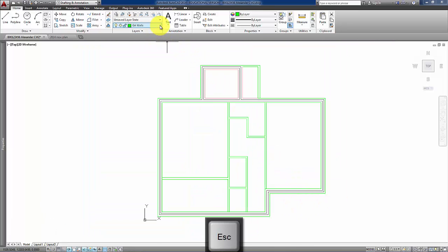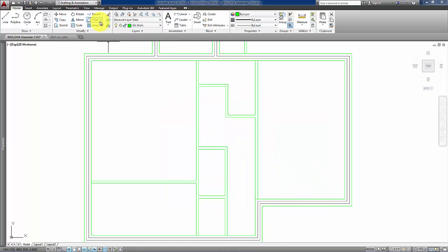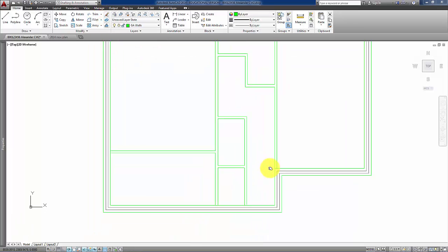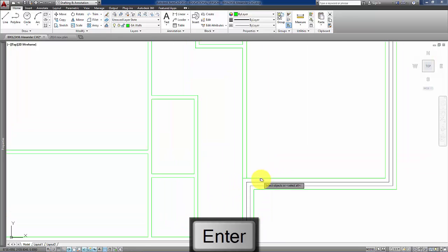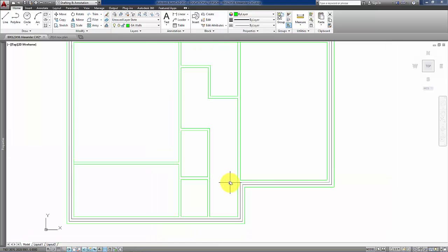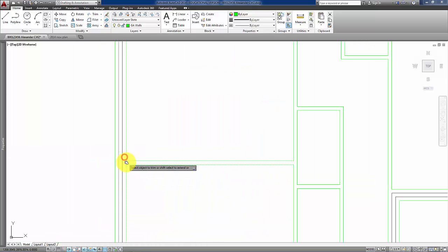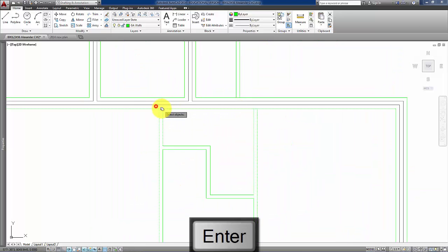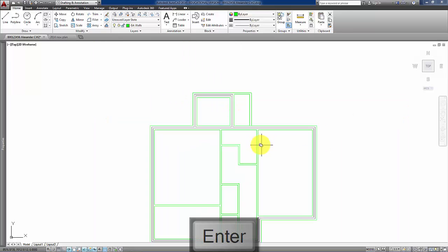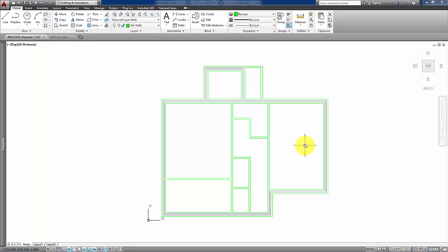At this point we should be able to hide again that room layout layer, and then we'll be able to go around and use the trim tool just to trim out where those walls meet the external wall. In this case the construction is blockwork for internal walls as well as the outside wall, so it's fine to trim out those gaps or leave the gaps. That should be the internal walls now complete. As I said, a relatively straightforward process when you have the room's layout to follow.